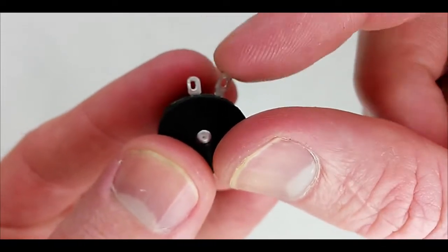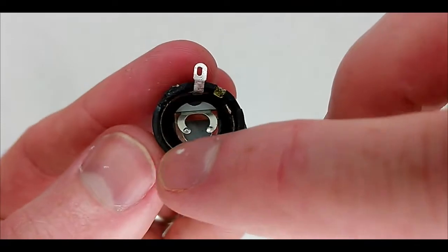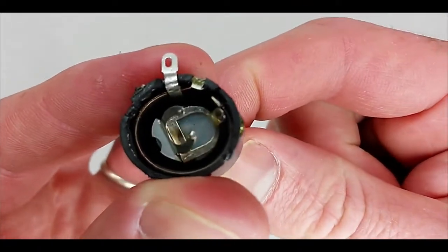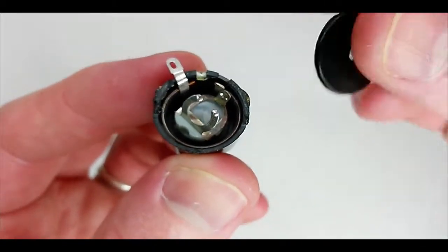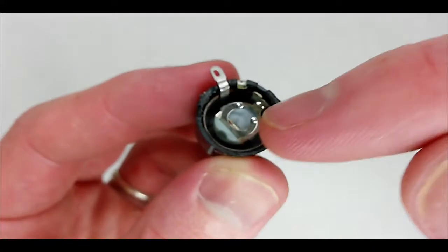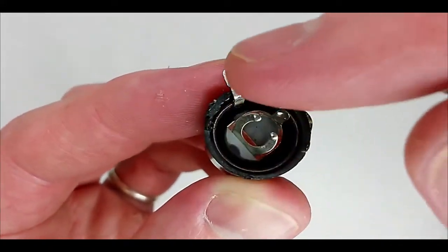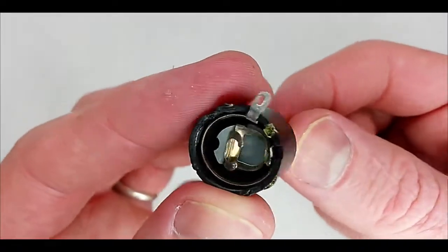So if I measure between there and there, I'd be getting 50% of the total resistance, because it's going through 50% of that wire. To get maximum resistance, I'd go all the way over to this side. So now between this wiper arm bit here, if I was to put that back on, we'd go from there. It has to go all the way through that resistance winding, all the way to there. And that's it. That's the internal workings of a rheostat.